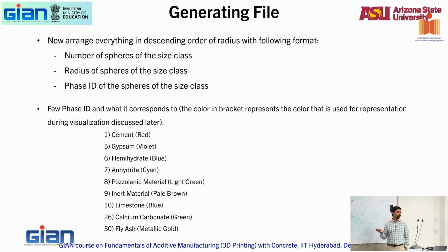I'll show you 4 different materials that I selected for the examples. I'll most probably not go into all 4, but initially for microstructure, it does not matter. If you select one for everything, it will still give you the microstructure. Later on, if you want to do the cement hydration model when it is developed, obviously you can't do that just by selecting one, because it will think that the limestone is also cement. So this comes into the picture for hydration, while for the microstructure distribution, there's no issue with having all the numbers the same. So you see these 3 things, right?